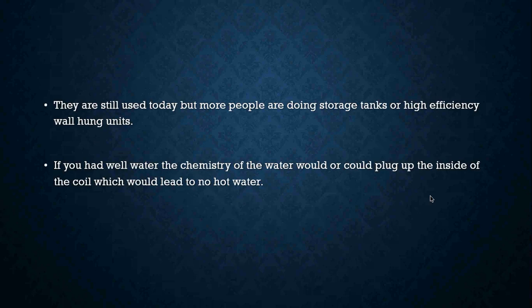If you had well water, the chemistry of the water could plug up the inside of the coil over time. Again, hard water was one of the biggest culprits with these old types of water coils. If you had a lot of calcium buildup, eventually the coil would literally just plug up and you would have absolutely no hot water whatsoever. In order to get it back, you would have to replace the coil.